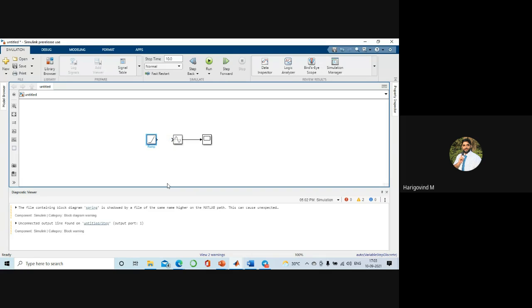Earlier I gave a step signal. So what was a step signal? A step signal goes from 0 to 1, so there is no change, right? You are getting 1 throughout, and that constant value is given to sine x. So sine pi, sine 180, is 0. So throughout the cycle, throughout the 10 seconds, this is the simulation time. This is the x-axis of the plot, described here. If you want 20 seconds or 30 seconds, the more time you give, the longer it takes to simulate. That's the only difference.